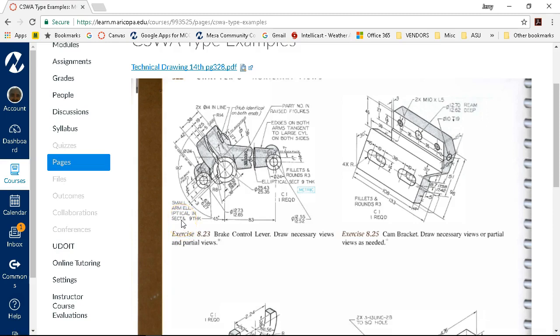Alright, so jumping into the cam bracket. This has some optical illusions because pretty much the back is flat from point to point, or reasonably planar with the T-slot, but because of the notch, it gives the illusion that this is stepping back some distance. So take 20-30 seconds and stare at it and make sure that you have a really good concept of what it is that you're going to draw if it's purely isometric.